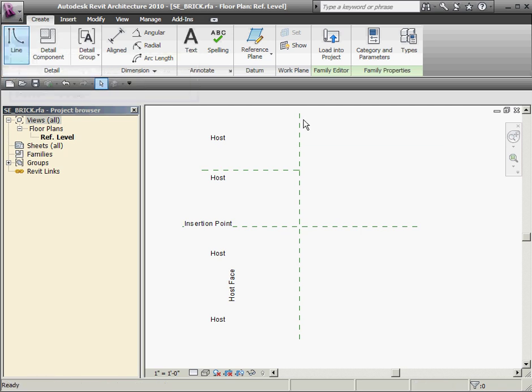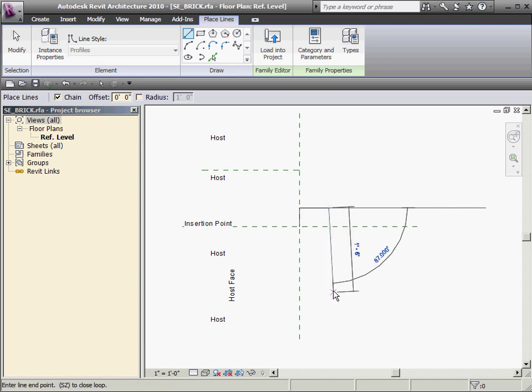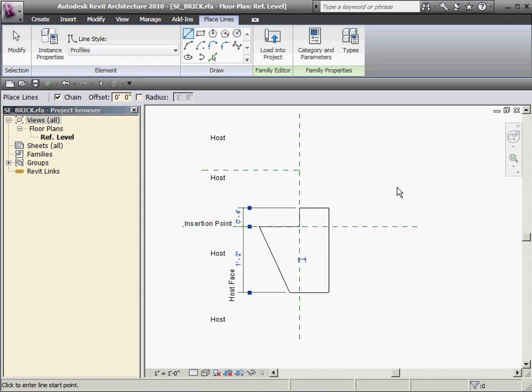Now what we have left to do is just some line work. Starting at the intersection here, well, you can start anywhere, but I'm going to go up about, I don't know, 4 inches or so, out about 6, let's say a foot and a half, 8, and bring it back around. Now, I've got a 4-inch dimension from the underside to here. I've got a 1 foot thick slab, which should give me an 8-inch drop. So that's about where we should be.